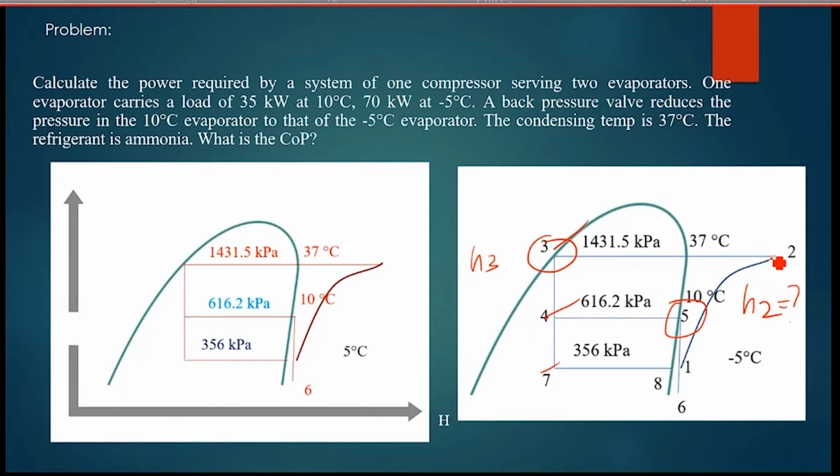Now here is the 2 beyond the saturation line. That's why we call this the superheat region, beyond this line of saturation. We can get that from here. Now look at this one. 1 and 2. You see here 1 to 2. What is the equipment involved? The equipment involved is the compressor. And what is the process involved?